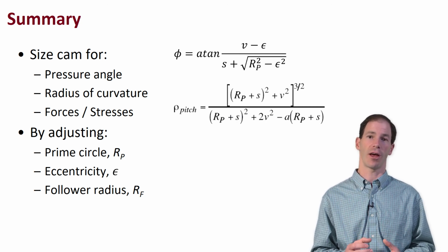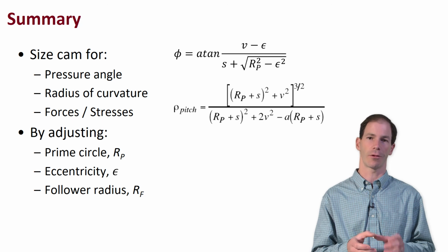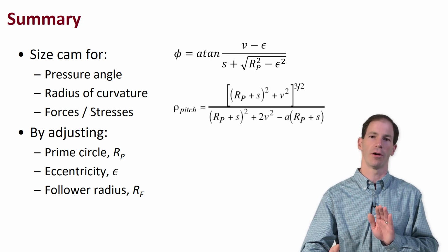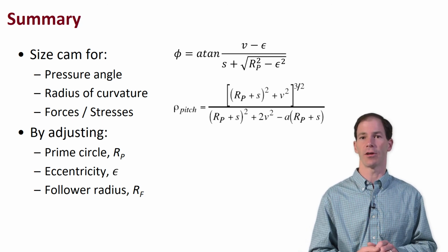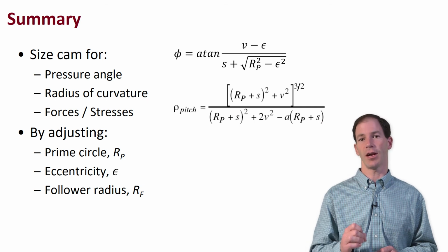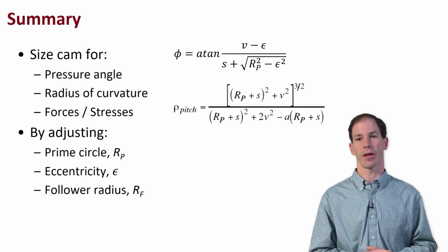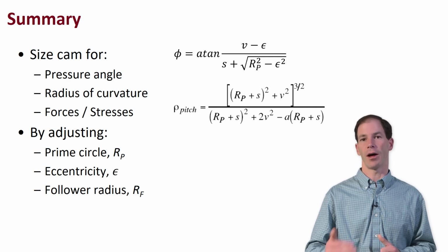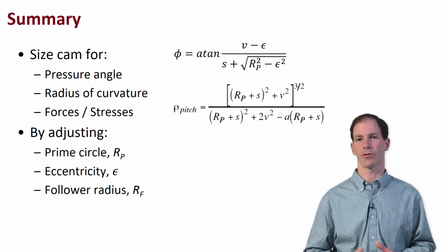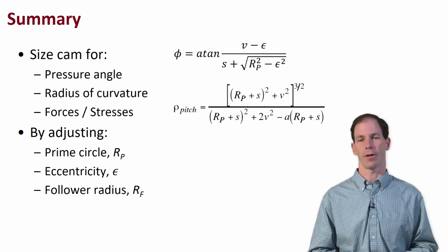And to do that stress analysis, we need to know the distance that we're acting, or the distance into the page of the follower, so how wide is it. Also the roller follower radius as well as the radius of curvature throughout the range of motion. So we'll then be looking at the contact stresses. We then want to move on to dynamic force analysis, material selection, how do we lubricate it, things like that.